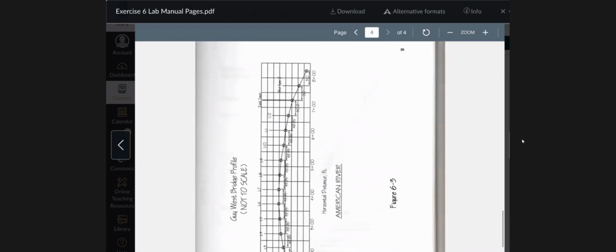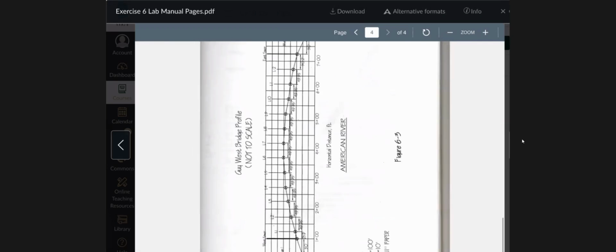And then label all the distances between the measurements, label the midspan, label the towers, label it just like it's shown here, and make sure you show a scale, okay? Put scale H is 1 inch equals 100 feet. V is 1 inch equals 10 feet. You don't have to put 8.5 by 11 paper. I'll know that it's 8.5 by 11 paper when I see it. Okay.